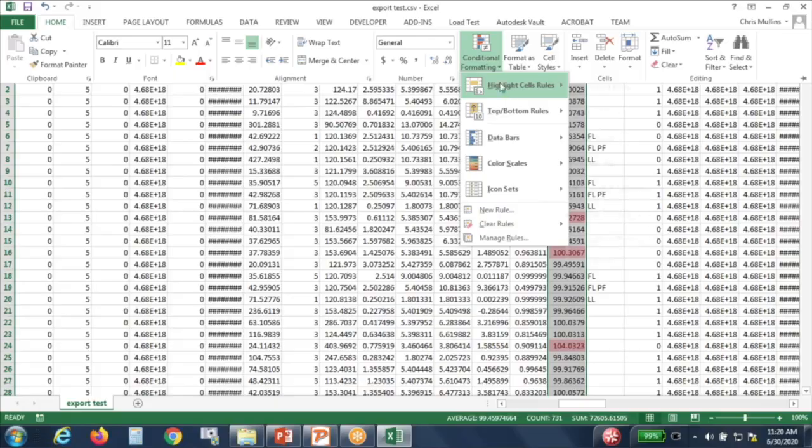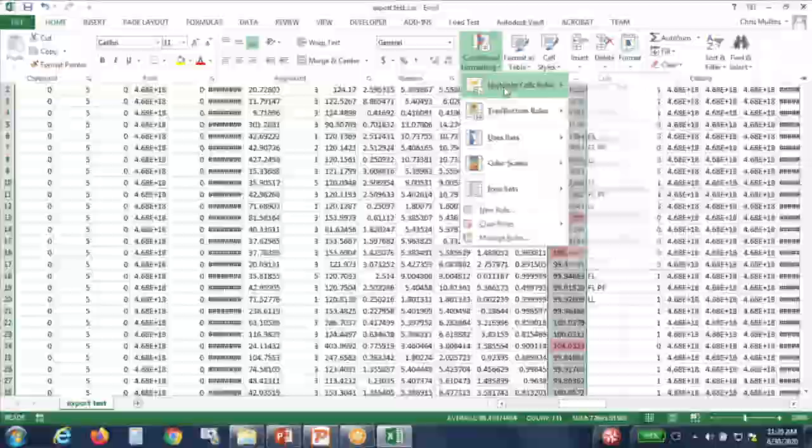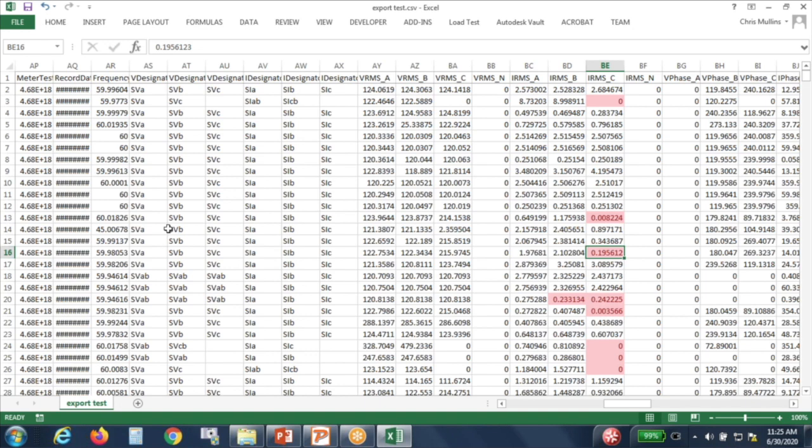If you guys ever have these 4-wire deltas that have a high leg C phase, we ran across a lot of these services that have no load on C phase at all. And so sometimes that can affect registration, because if it has 0 amplitude on one phase, it could affect it. So it kind of gives you a tool to help determine what's going on.